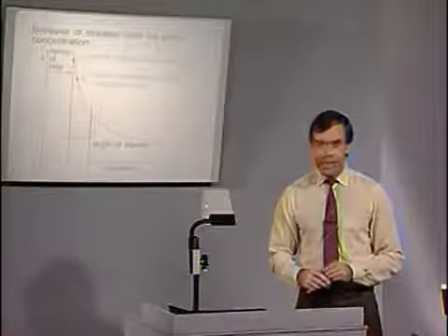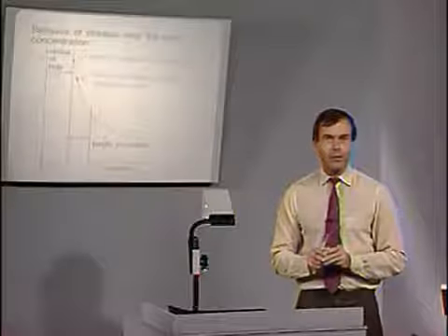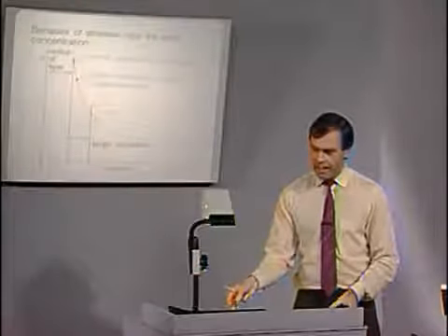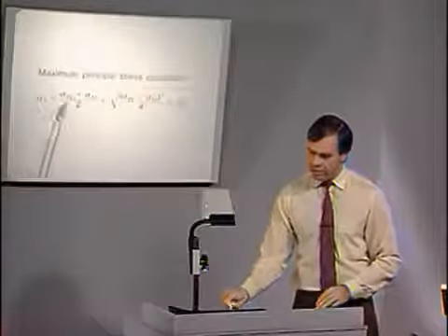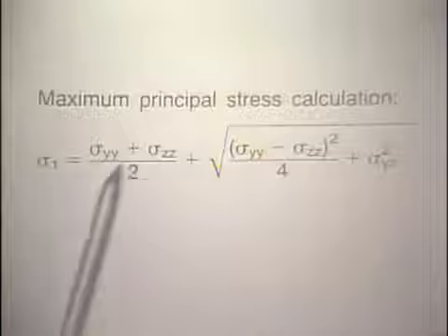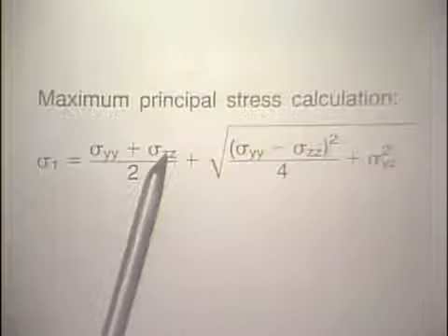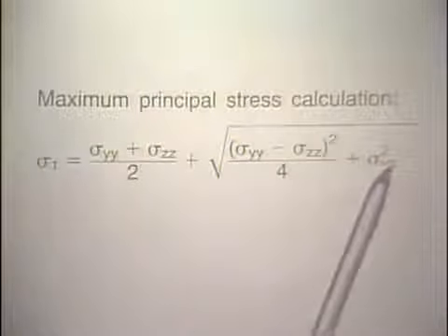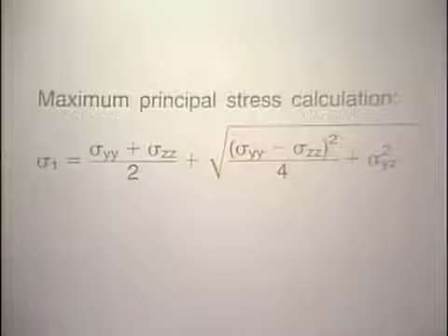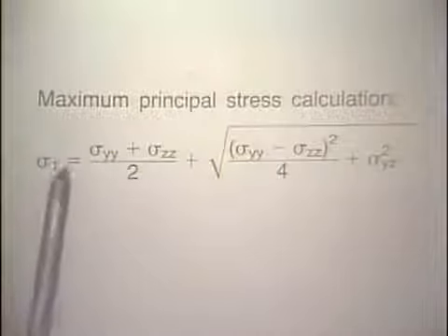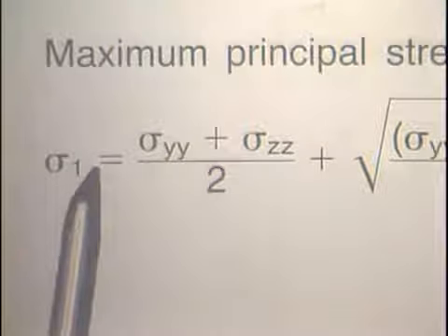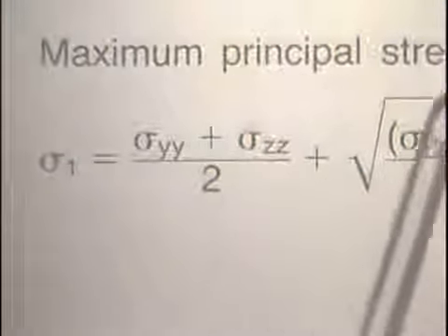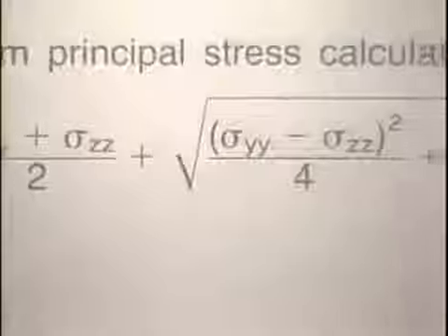We can ask ADINA to calculate the stresses at the nodal points, and then we can ask ADINA-PLOT to enter with these nodal point stresses into this formula here, where sigma yy, sigma zz, and sigma yz are the stresses at the nodal points. ADINA-PLOT calculates this sigma 1, which is the maximum principal stress at that nodal point.